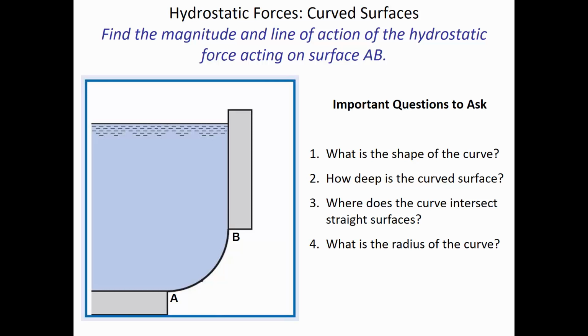Then we'd go down where the pressure is a bit higher, and ask what's the pressure times area there? And so we want to integrate all of that and find the one resultant force acting on that gate. And we want to know not only the magnitude, but also the direction and the location. The hydrostatic force: magnitude, direction, and location.